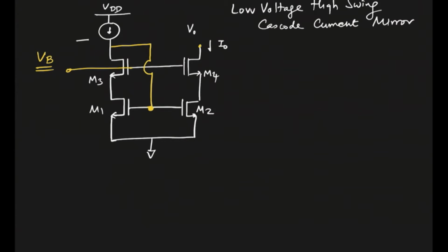So what is R input here? This is R in, and this is R out. What I would like you to do is use a small signal analysis for this circuit and prove to yourself that R in looks like approximately 1 divided by gm1. This is something you have to do yourself using small signal analysis.